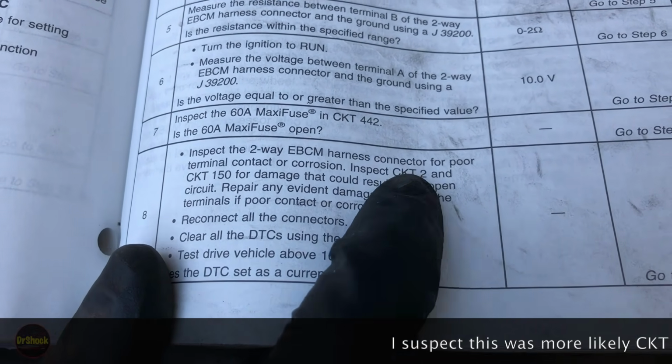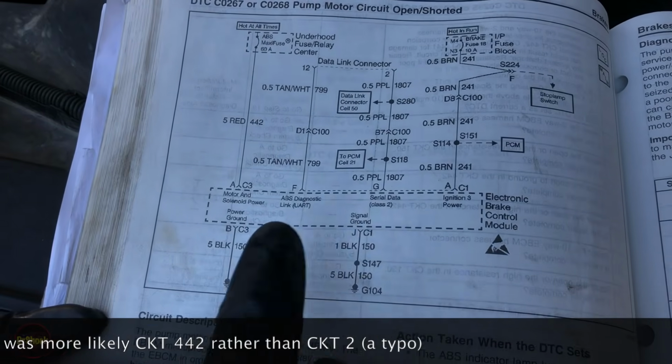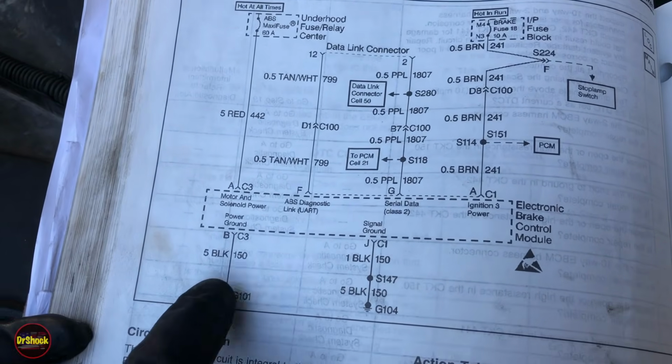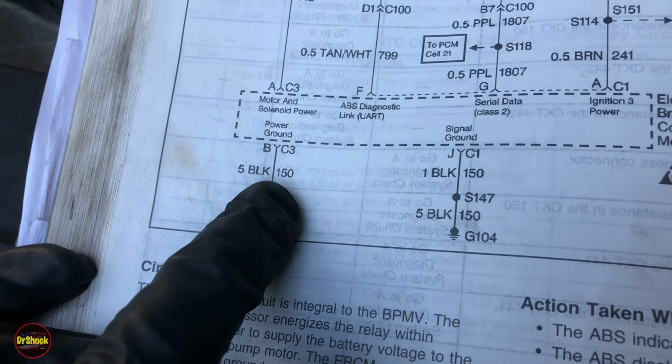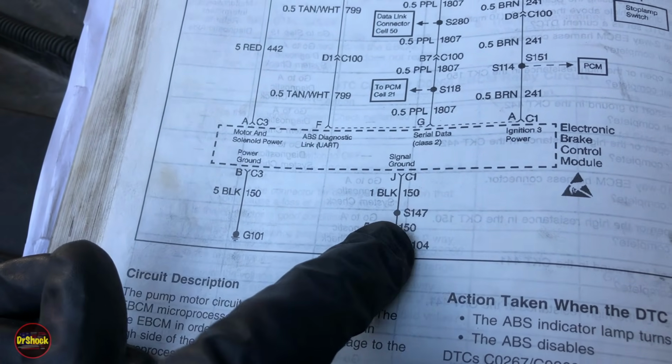It's circuit 2 and circuit 150. Now, still looking at the schematic, I don't see circuit 2 called out anyway. So, even though I misspoke, we still have to go find it somewhere else. But I did want to add that the ground circuit 150 that they're talking about is G101 and G104. So we're actually going to do both of these, right?